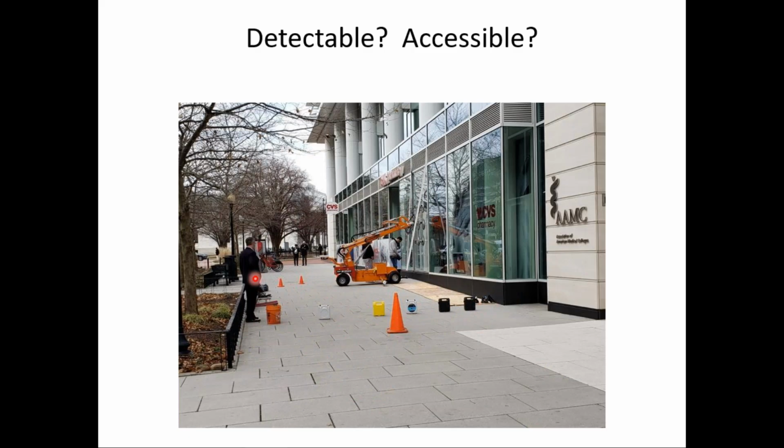But one thing you can't see is to the left here of these trees, there is along the curb about a 5-foot wide strip of sidewalk to serve, I guess, maybe the parking meters and things that are along the street, the on-street parking. So actually this is accessible. It's just a matter of providing some cues, providing information to pedestrians so they can find that sidewalk here on the other side of these trees.